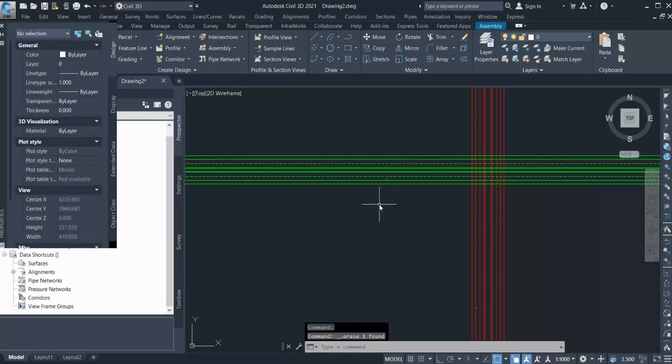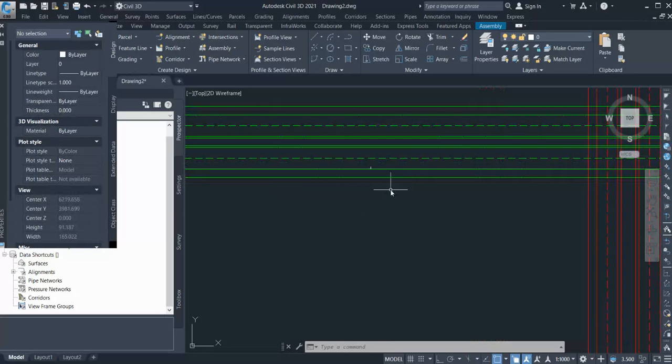Second thing is the nose angle, or you can call it the diversion or merging angle. Your slip road, or you can call it the loop, will be diverted from the main line between 3 to 5 degrees, so it will be smooth.